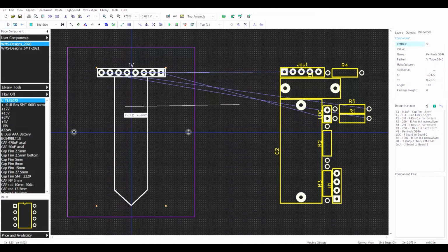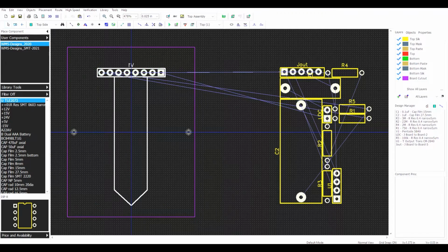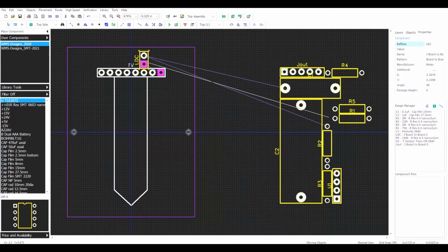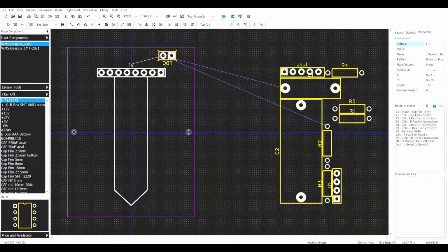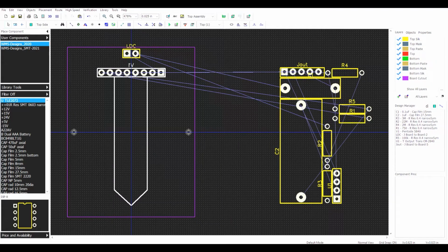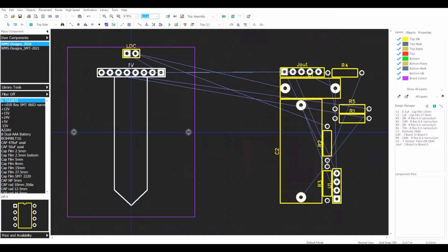I want to have a little bit of room, because the one thing I know I want is I want the capsule to sit pretty far at the top. So I'm going to drag it over, and just like in the schematic program, I can hit the R button to move things around. That's good. And typically, I would usually do 0.1 inches or so to align things. That usually works pretty well. And then occasionally I'll go smaller just as I'm fine tuning. But for the majority of the layout, I'll do that.